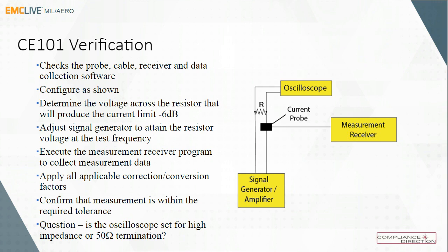But the idea is that putting an oscilloscope in 50 ohms in parallel with the R changes the value of the total R, and current will change. So no longer is that voltage valid. So the whole idea in deciding for yourself whether the oscilloscope needs to be 50 ohms or not is determined by, we look at the circuit and say we do not want the measurement equipment changing the values of the measurement.